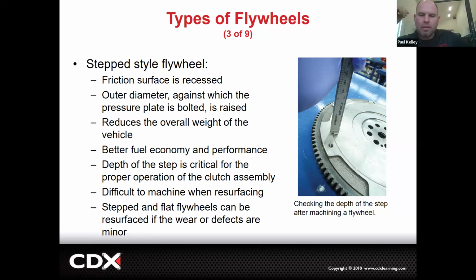Come on now, give it to me. One was slipping, so this one by default would probably be dragging. Yeah. All right. So what I mean by dragging, you push the pedal down, that should give your disc enough room to be totally loose, and it should stop your transmission from turning. Cool. But instead, now we only have 20 thousandths clearance because they messed up and they over machined the step and under machined the friction.